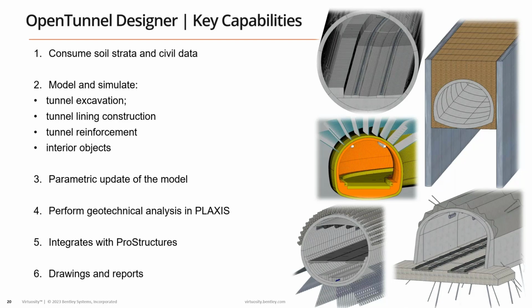We are supporting tunnel lining construction for conventional tunnels, for TBM tunnels, and also, with a given efficiency, we can create cut and cover. Even if the modeling does not have a high level of detail, it all depends on what the user wants to achieve with his template. As you can see here, this is a very simple option where I have the piles, my cut, my soil, and my tunnel, but whatever the user is drawing in the tunnel template, we are able to extrude it and create 3D models in the 3D space.